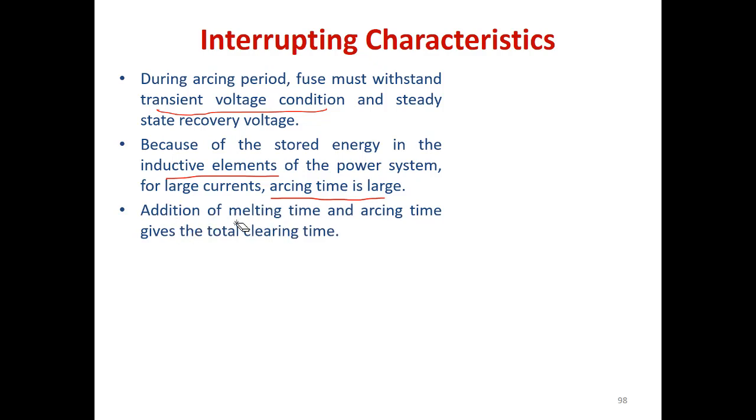So the addition of melting time and arcing time gives us the total clearing time. The melting time plus arcing time is the total clearing time. So this gives us the total clearing time of the fault.